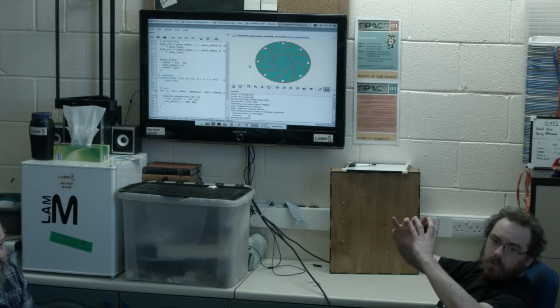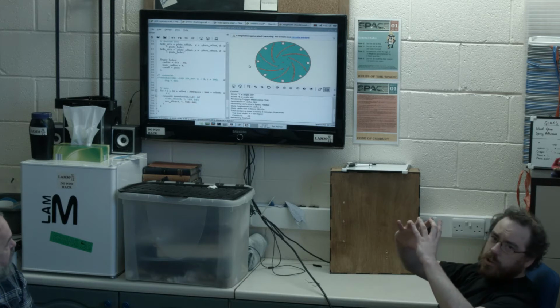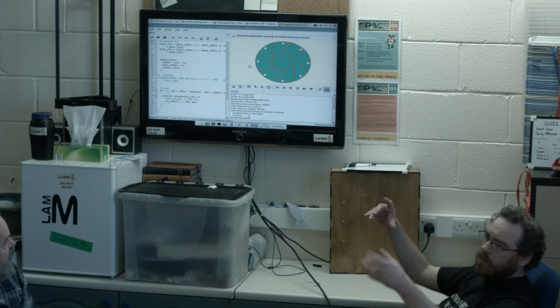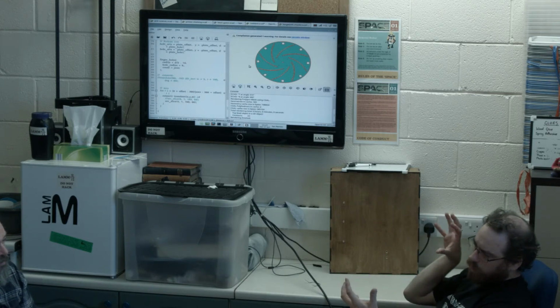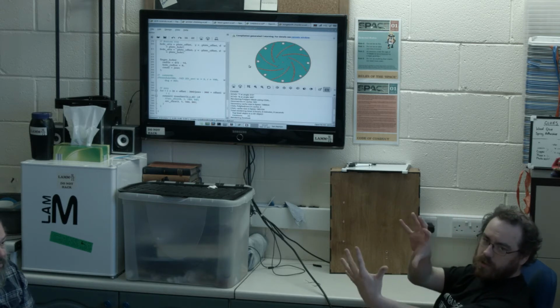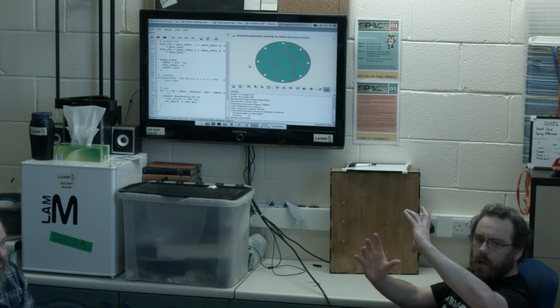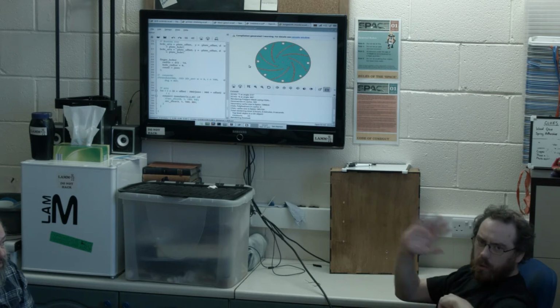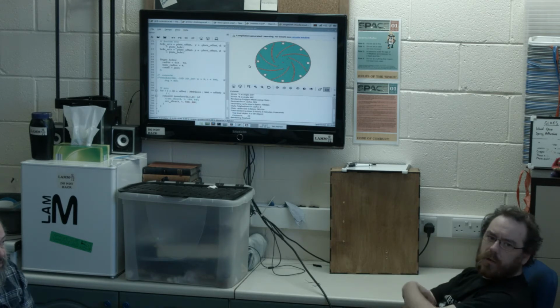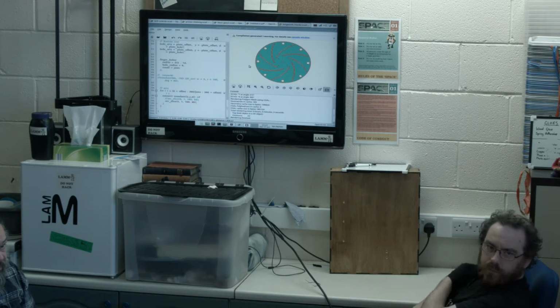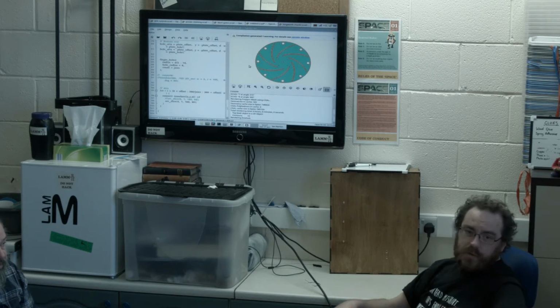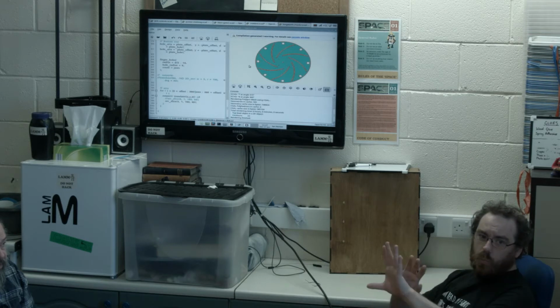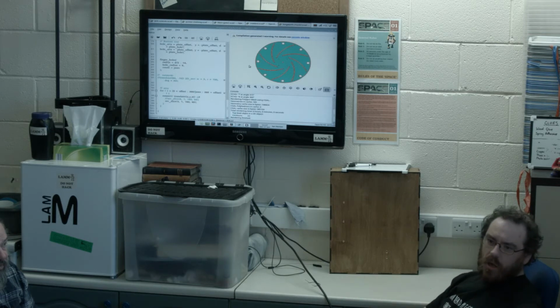Oh, I see. So it's a chuck. It's a Longworth chuck is the design. So basically, when you take your bowl off, you can put it bowl open end first onto the Longworth chuck, clamp it, and then turn the bottom, because you can't turn the bottom any other way. You clamp it on the outside, open end, so you can actually work on the bottom of the bowl.